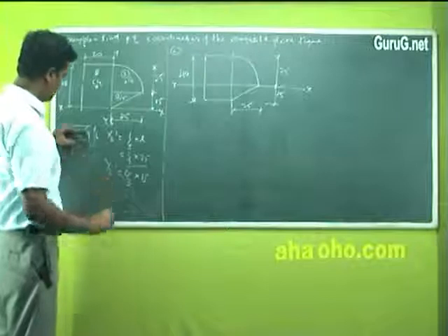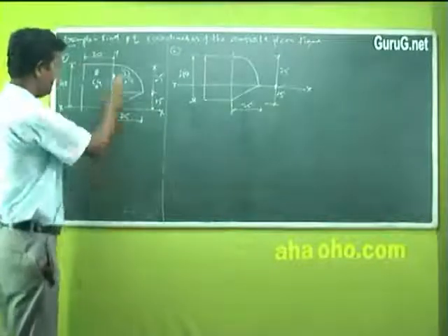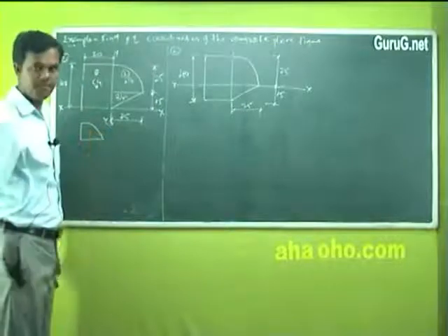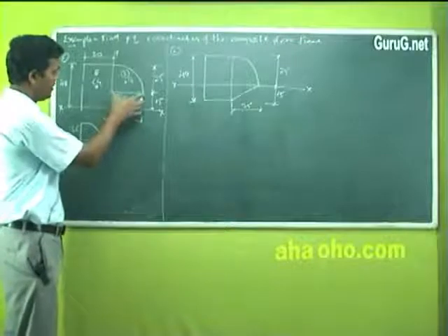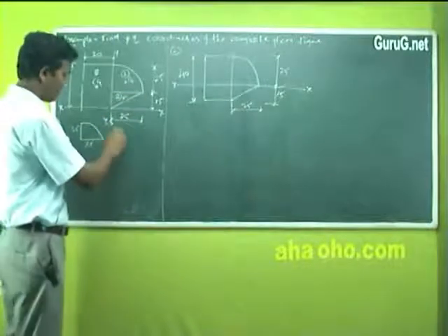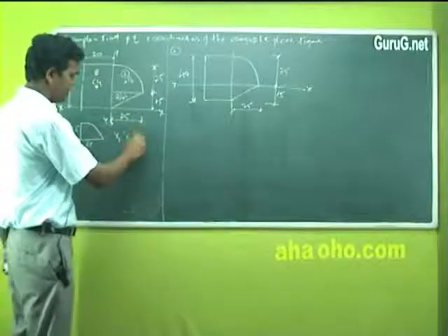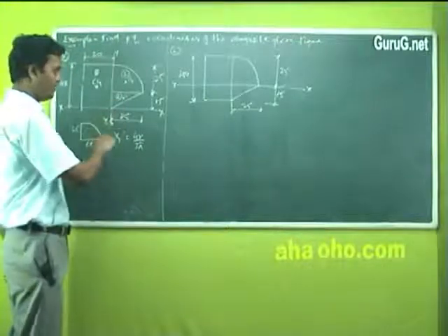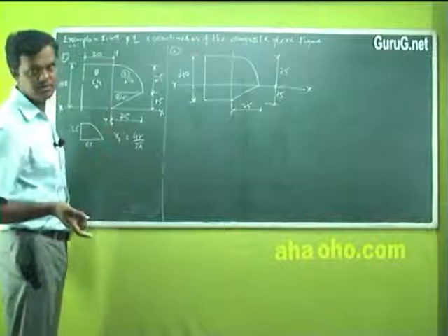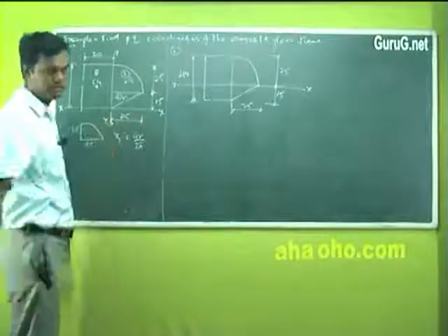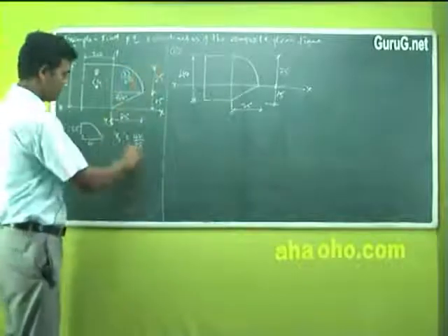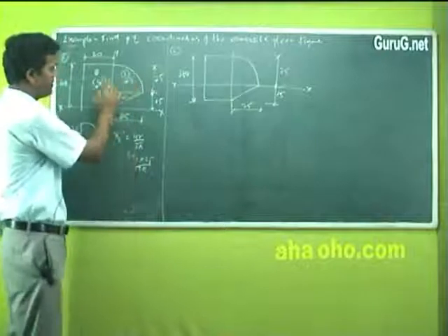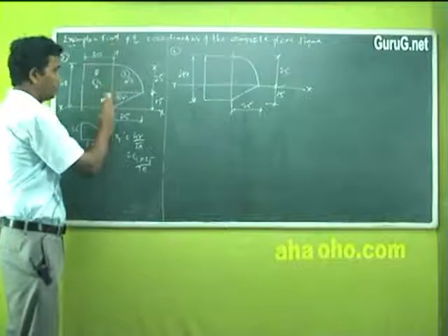Is it okay? Then that's about the triangle. Then this quadrant. The quadrant shape is like this. Again the value is, this is 25 given, and this is how much? 25. The formula for the quadrant, x dash, x1 dash, whatever it is, 4r by 3 pi is the x value from the standard formula in the book. But whether this value should be negative or positive is the question. What is the radius of this one? This radius is 25 only. Here 4 into 25 by 3 pi. The x value is on the right hand side because I am going to find the CG, x values means traveling towards the x direction. So after the yy axis it is on the right hand side, so it is positive.